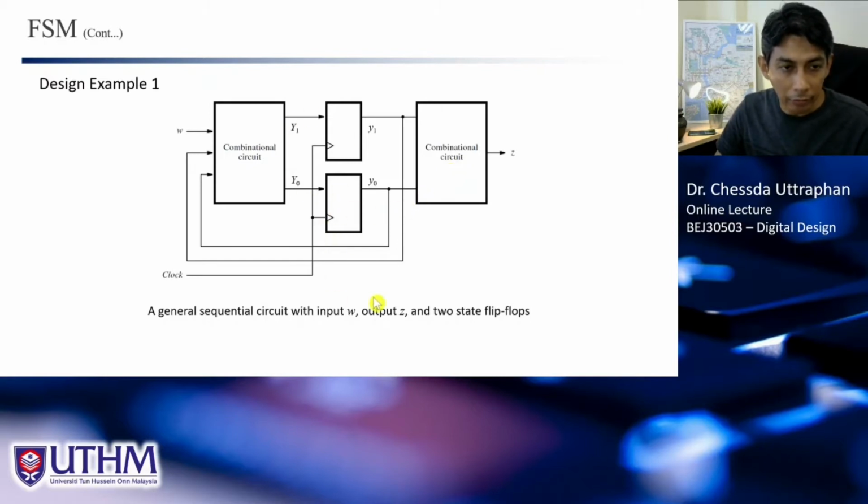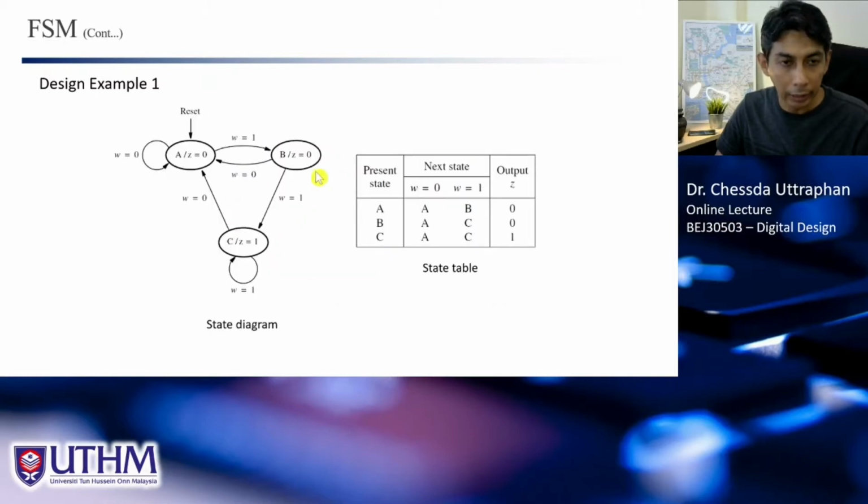If we have 3 flip-flops, for example, just add another flip-flop, and we just have the feedback to this, and of course we have another y, which is y2, and we can connect just like this. So still easy. So now let's write the code to describe this block with the behavior like this.